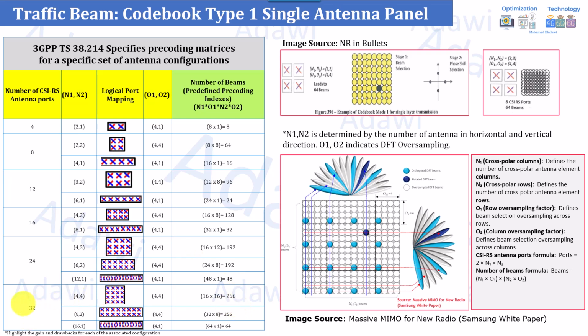So if you make it as a wide beam, first of all, because it's 32 CSI-RS, this means you will have fewer sub-arrays in transmission, which means fewer antenna elements per each of the port transmission. So this means you might have less coverage compared to the 8 ports. Because with 8 ports, if it's beamformed, it has 2 advantages in terms of coverage. It can go to a higher distance, not necessarily to cover a wider area, but to go for a larger distance. Why? Because 8 ports means that you can have 4 CSI-RS, you can have 4 wide beams, and at the same time, this means you will have more sub-arrays and more antenna elements transmitted per each port, because now the antenna itself will utilize the existing 64T, 64R antenna elements in there to just utilize it for 8 ports.